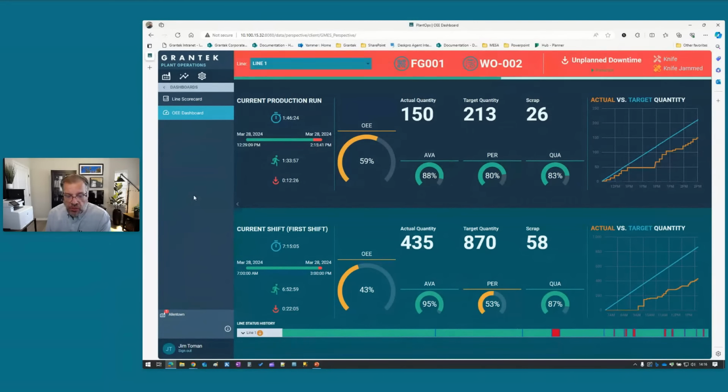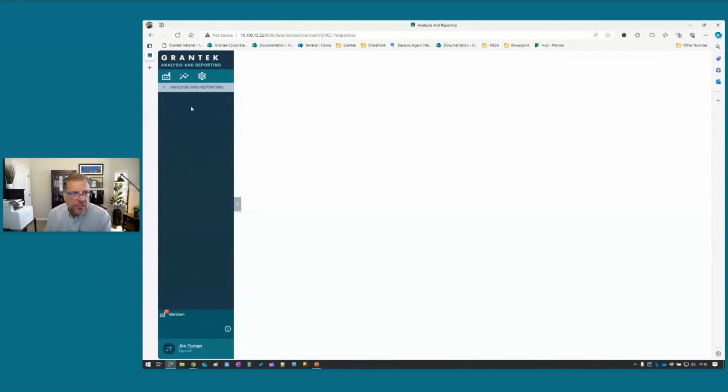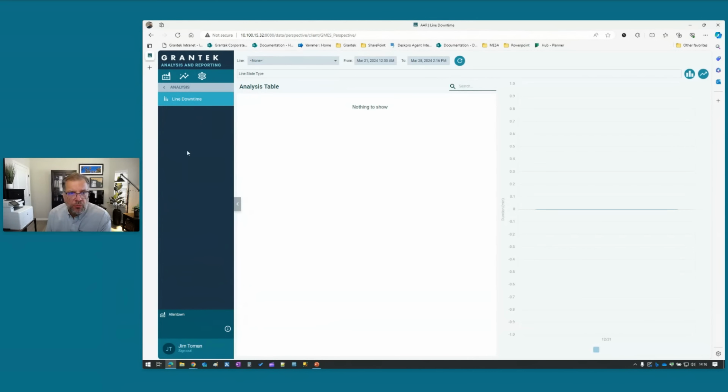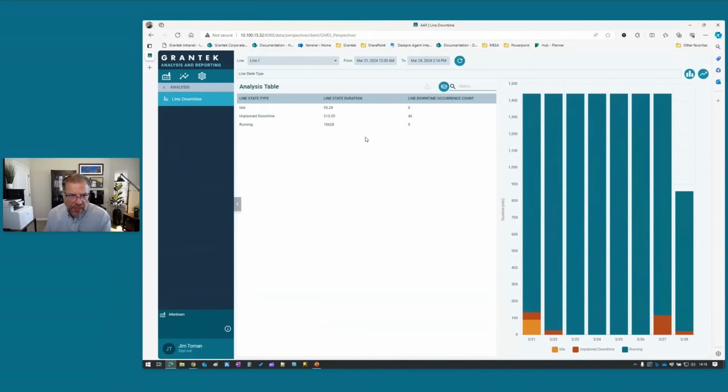Let's say we want to learn a little more about the OEE impact of this unplanned downtime. We want to learn what we can do to make that better. We can go to our analysis and we can look at our analysis reports. We want to look at our downtime report specifically for line 1. And when we look at line 1, what we'll discover is that we have had 92 minutes of idle time overall, and we have a low occurrence count of that.